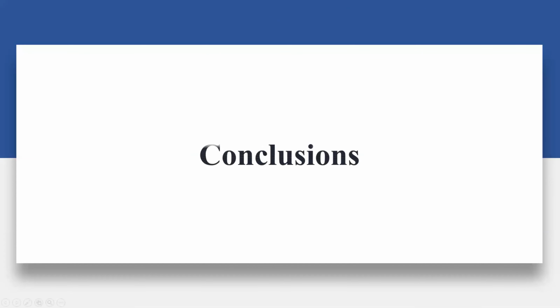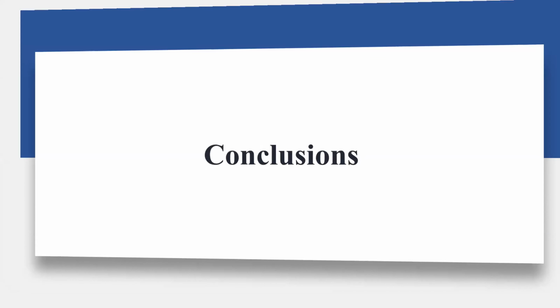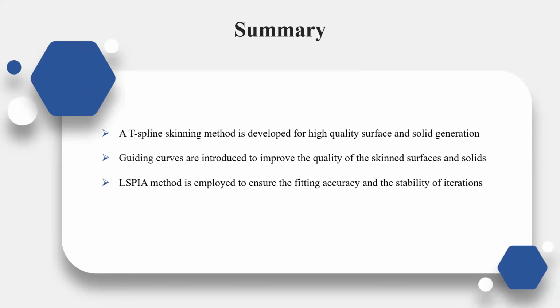Now, we give some summaries of our work. First, a T-spline skinning method is developed for high-quality surface and solid generation. Secondly, guiding curves are introduced to improve the quality of the skin surface and solids. The last one, the LSPIA method is employed to ensure the fitting accuracy and the stability of iterations.